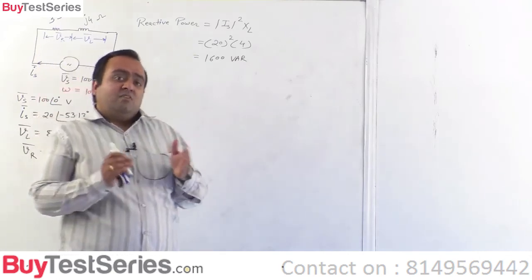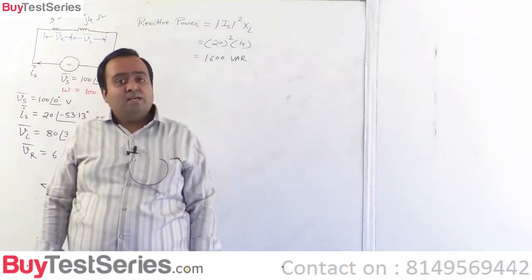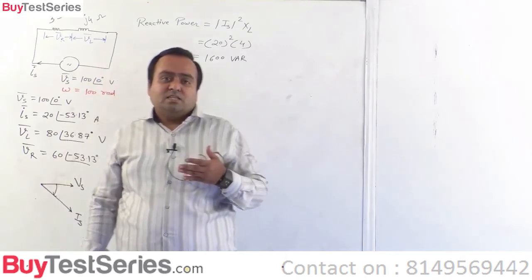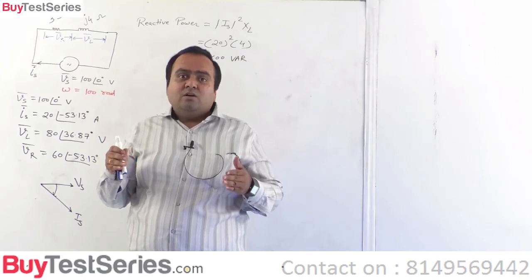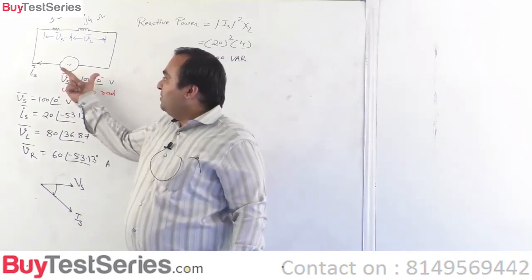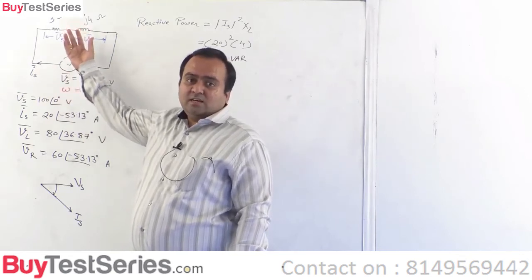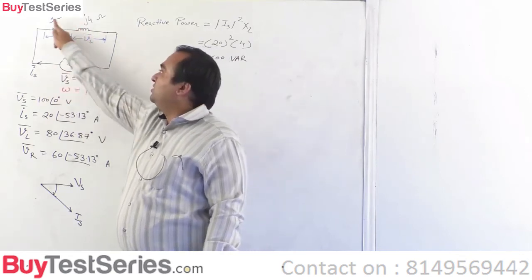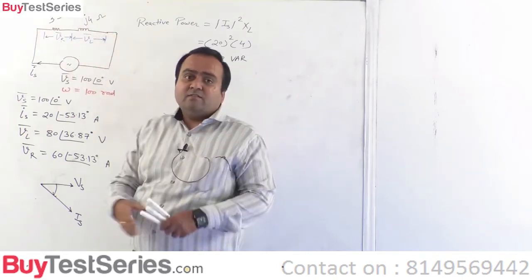हम लोगों ने पावर बैलेंस किया डीसी सर्किट्स में, वही पावर बैलेंस हम यहाँ भी कर सकते हैं, but we must understand here we have to balance P and Q both, right? Because whatever is the active and reactive power supplied by this source has to be taken by the circuit elements. This would absorb active power always, and this would absorb reactive power.